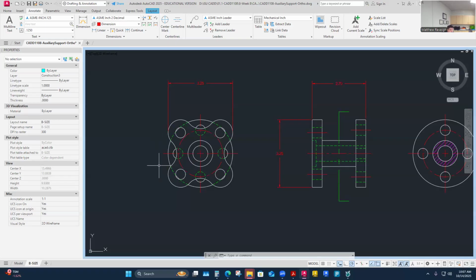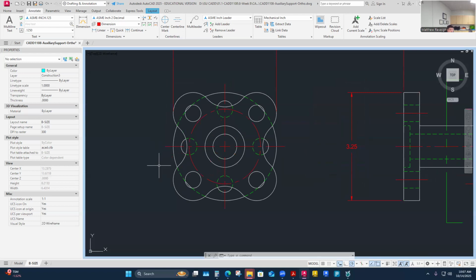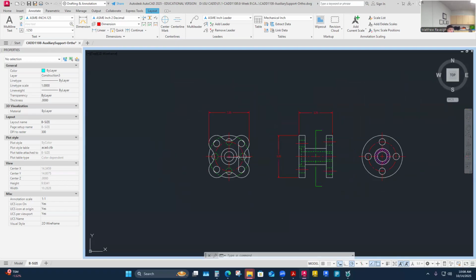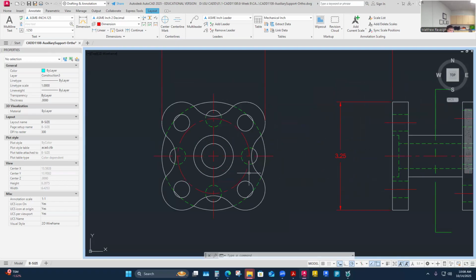That's what I'm doing here. Your dimensions don't always control a part sufficiently. But I do like this crosshair that I'm going to work off of. So let's think about it: I've got some overall diameters, but they're not based off of left to right or right to left. Nothing's better than the other. But if I say it's from center out this way and center out that way, that might be a good place to base some of the outer profile.